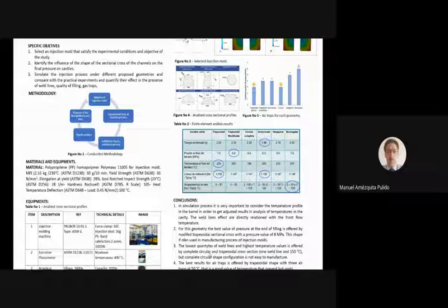The equipment used were an injection molding machine Turbo 50 RS1, clamp force 50 tons, injection shot 36 grams of PS, barrel heater with 3 zones of 100 watts each one.